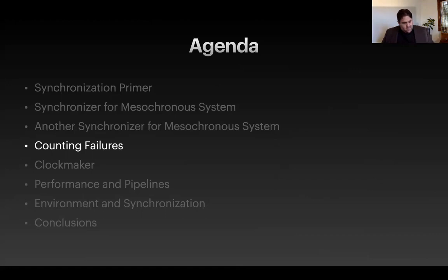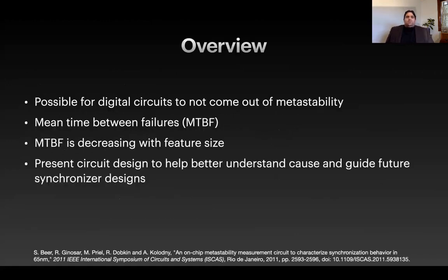Next, this almost sounds like a heavy metal song, but I named it Counting Failures, and I think you'll see why shortly. The authors in this paper realized that it's possible that some digital circuits just may not come out of metastability. And the way this is measured is in a metric called mean time between failures, or MTBF.